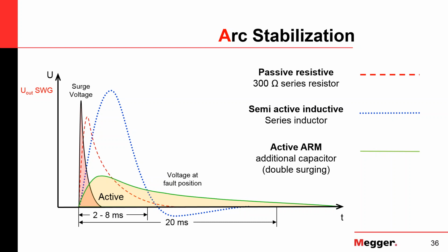So why do you do this? The reason is you want to maximize the chance that one of the radar pulses is actually hitting that arc when it's standing there, when it's burning there, for only a few milliseconds, and so you can actually see where the fault occurs. These TDRs that are involved in fault location are not your typical handheld TDRs.